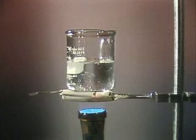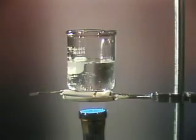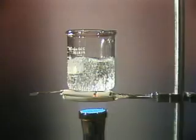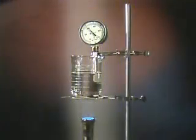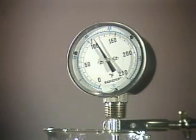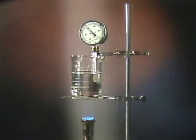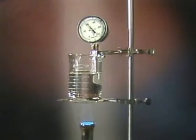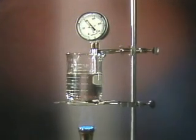What do you think normally happens when phase change occurs? Normally, whenever a phase change occurs, heat transfer takes place. We'll use this beaker of water to demonstrate a phase change and to identify a couple of types of heat transfer. As the water is heated, heat is transferred to the water, and its temperature increases. The heat that is transferred when there is a temperature change is called sensible heat. In other words, sensible heat transfer is heat transfer that can be sensed by thermometers and other instruments as a change in temperature.